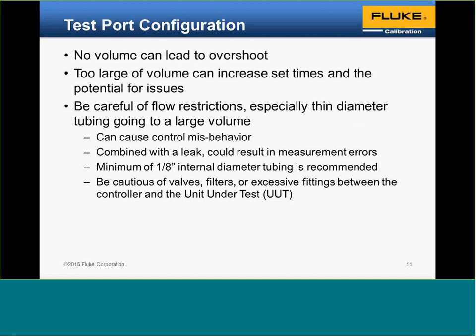To the test port. This is the output of the controller. It receives supply pressure from our regulated nitrogen bottle with the different valves and so forth. Inside the instrument, it's regulating that pressure, sending it out to the test port. And this gives you a controlled, steady pressure on that test port.